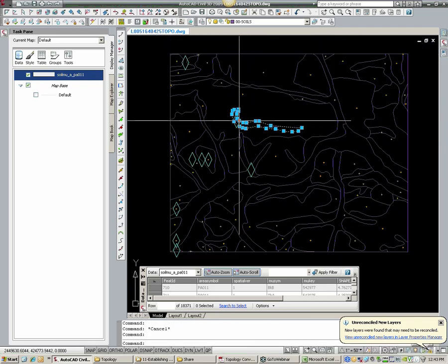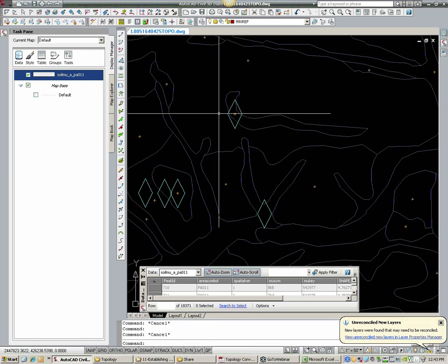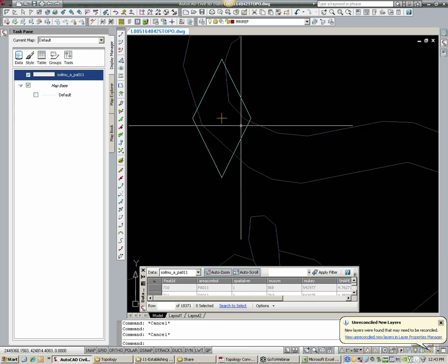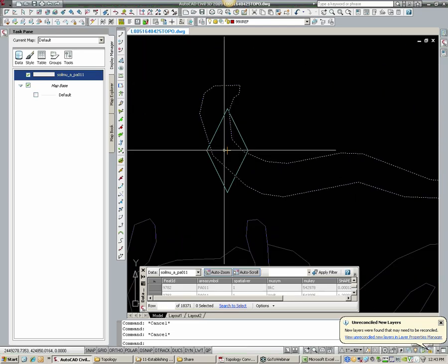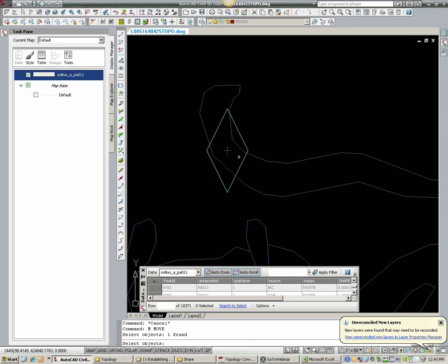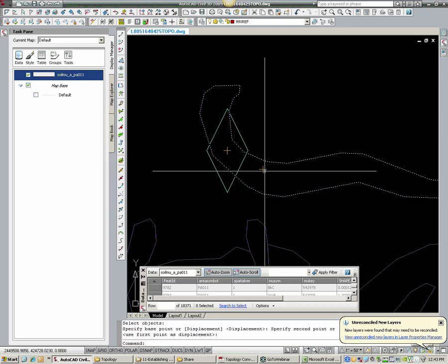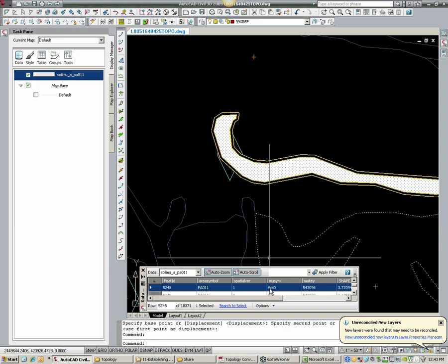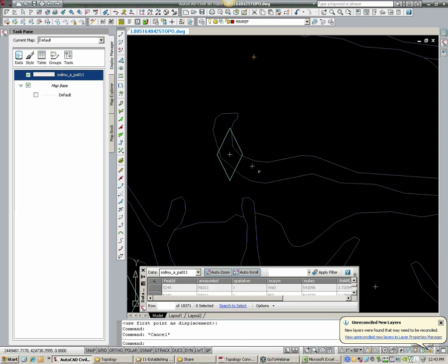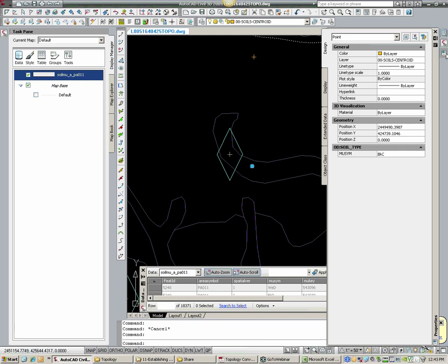And then we don't know why that's happening there. So why is this one here? Everything looks okay. Well, it's again this whole big surrounded area. Actually put a centroid, and if you hit the move command and move one of these, they're actually 2 on top of each other. So which one's right? Well, I'm going to click on this soil type. This is supposed to be WED. I'll click on that little centroid there.